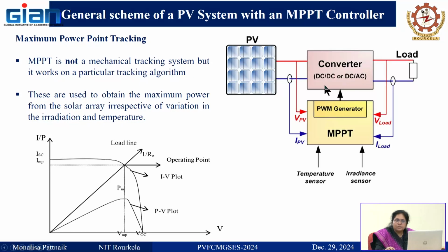So before coming to the technique, what is behind it, and what are the possibilities of converter? I'll cover only DC to DC converters. Already I told the options are buck converter, boost converter, buck-boost converter, SEPIC converter, Cuk converter, any type of converter depending on your application area or your requirement, simplicity, whatever. We will see that when we go for this MPPT operation.